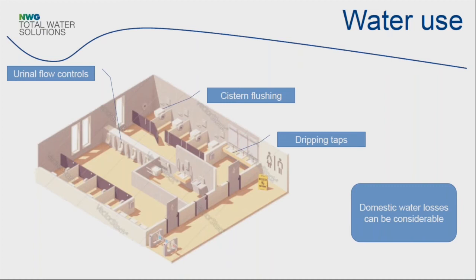The lack of water from the urinals meant that what reached the sewage works was less diluted than it had been, and that caused problems at the sewage works. It actually meant the sewage works wasn't complying with its discharge consent to a local river. So the client took out all of their waterless urinals and put the water flushed ones back in. That was a failure of the optioneering process, because the impact on the sewage treatment plant hadn't been considered during optioneering.